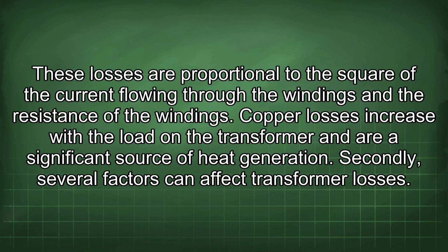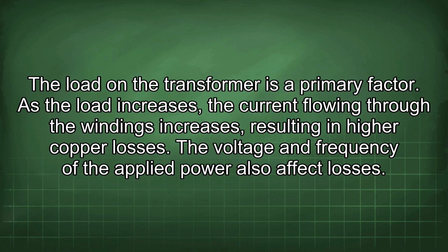Copper losses increase with the load in the transformer and are a significant source of heat generation. Secondly, several factors can affect transformer losses. The load on the transformer is a primary factor. As the load increases, the current flowing through the windings increases, resulting in higher copper losses.